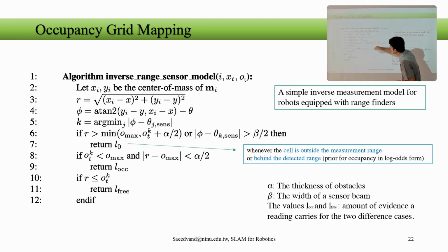These three ifs represent those three conditions. Again, I'm measuring, and the obstacle is there, so everything after that is free. That's the first term. Then the obstacle itself, by calculation of the grid size, can be partially covered by the obstacle. Whenever it is, I'm calculating with this if over here whether it's inside that grid cell, maybe it can be here and can be here if you consider it as a grid cell. So if it's inside that area, I can say it is occupied. Otherwise, all the grid cells that are in the way to reach that are free.